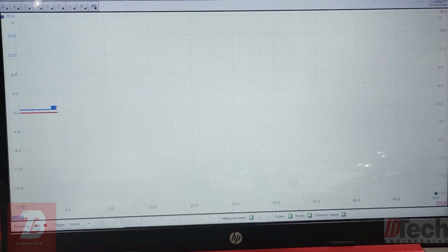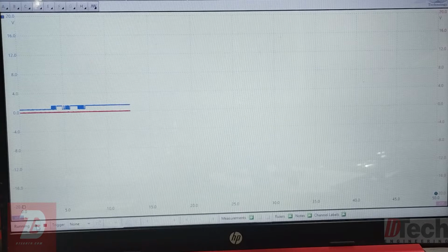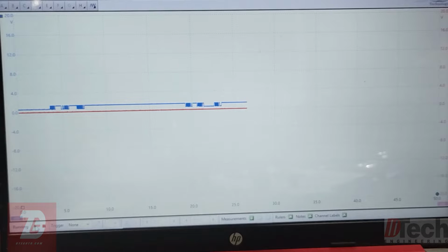Alright, so I am spinning the right front, and you can clearly see the left front signal, which I have on channel A. I do have that on what would be the known good. This is a front wheel drive, so both front wheels are spinning when I spin either one, it looks like. But I'm sitting here spinning the right front, and nothing on the red trace.